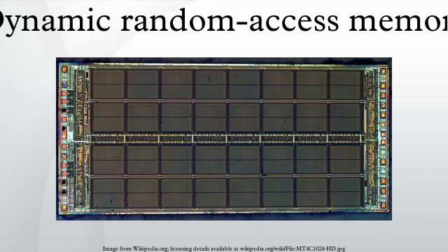Although BEDO DRAM showed additional optimization over EDO, by the time it was available the market had made a significant investment towards synchronous DRAM, or SDRAM. Even though BEDO RAM was superior to SDRAM in some ways, the latter technology quickly displaced BEDO. Multibank DRAM. Multibank DRAM applies the interleaving technique for main memory to second-level cache memory to provide a cheaper and faster alternative to SRAM. The chip splits its memory capacity into small blocks of 256 kilobytes and allows operations to 2 different banks in a single clock cycle.